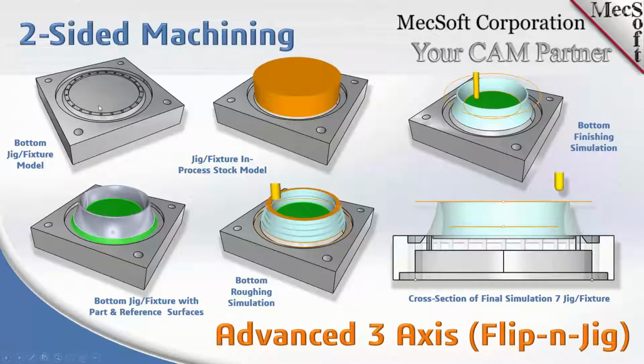So if you start on the left side at the top, we have the jig or fixture, and you'll see that it has an area for the part flange to sit on, and it's got all these holes around it, and it's got holes in the corners. Optionally, if you want to fasten this down to your table, you can use the holes on the corners, or you can hold it however you want to hold it. If you're using a vacuum table, these holes will help hold the part down, and I'll show you this in more detail in the actual part file.